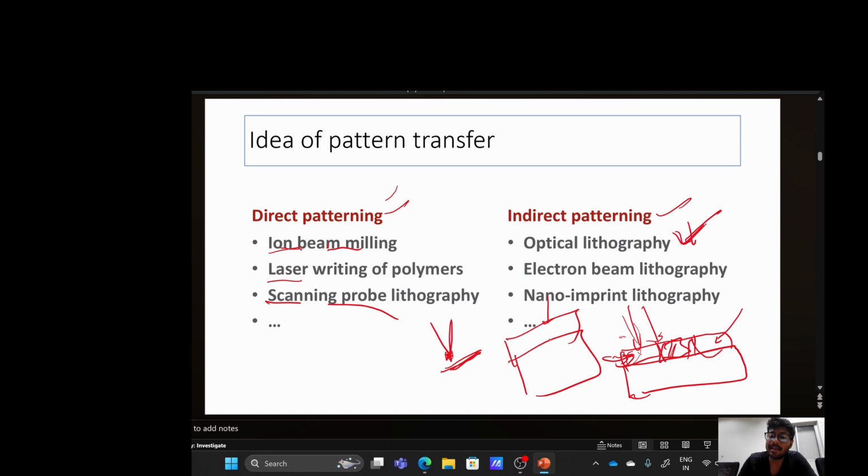That's fine. And electron beam lithography, which uses indirect patterning. This is also pixel by pixel, because you use an electron beam to write over the sacrificial layer, over that intermediate layer, and then you develop it, and that pattern is transferred over the substrate.